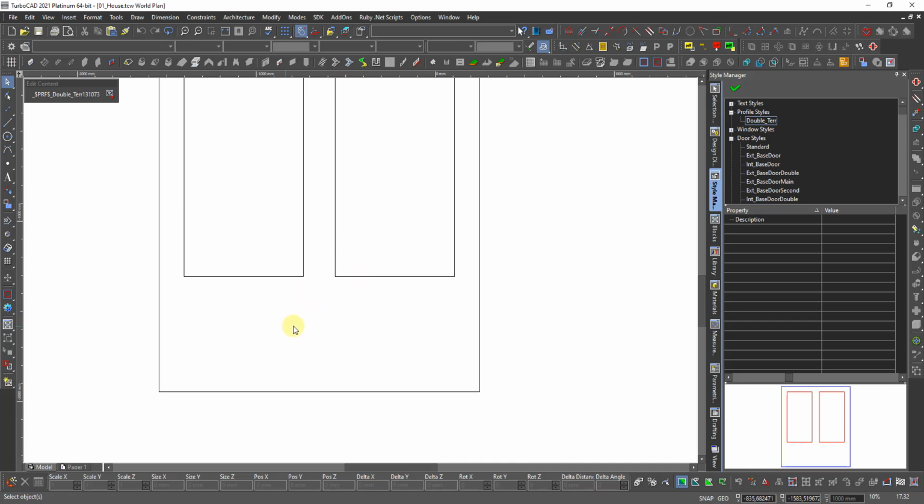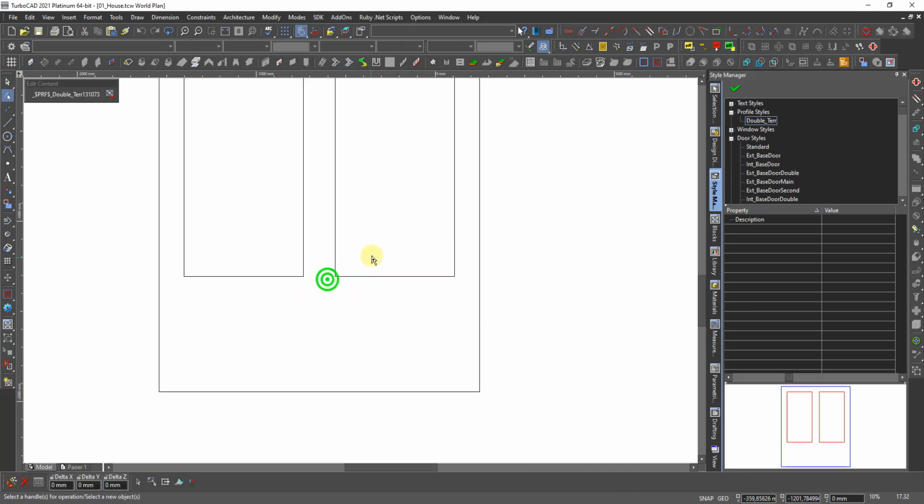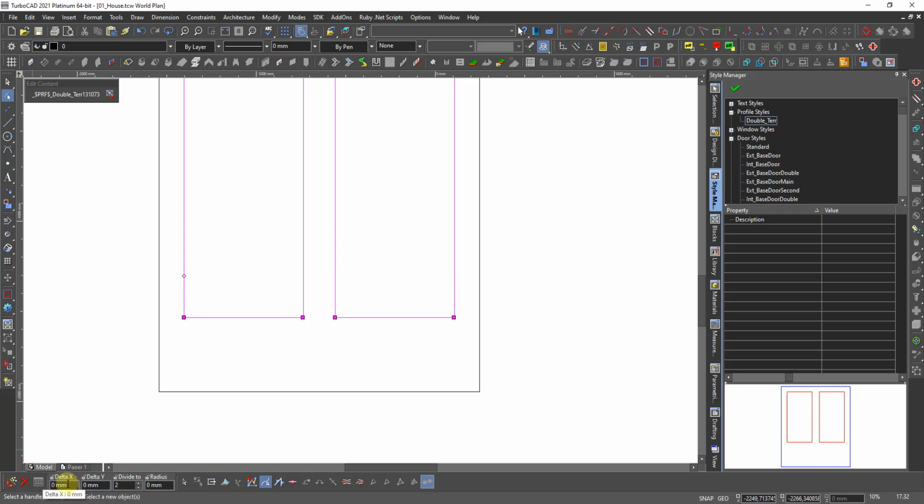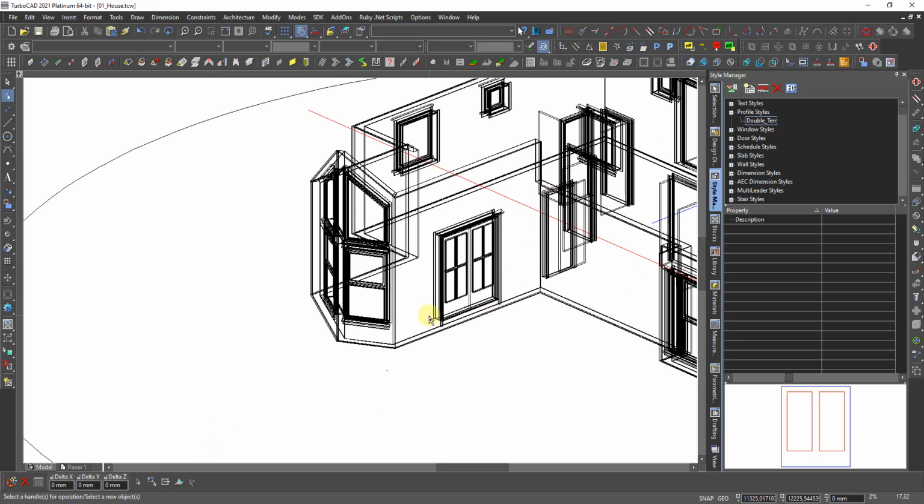I go with the edit tool, I take this tool, I can take this there. Because it's 220 plus 10, so it's minus 230 in delta Y, I assume. Minus 230, there it should be. And then I say save, and now I go down there, you see, the muntins have changed. I go out from edit,